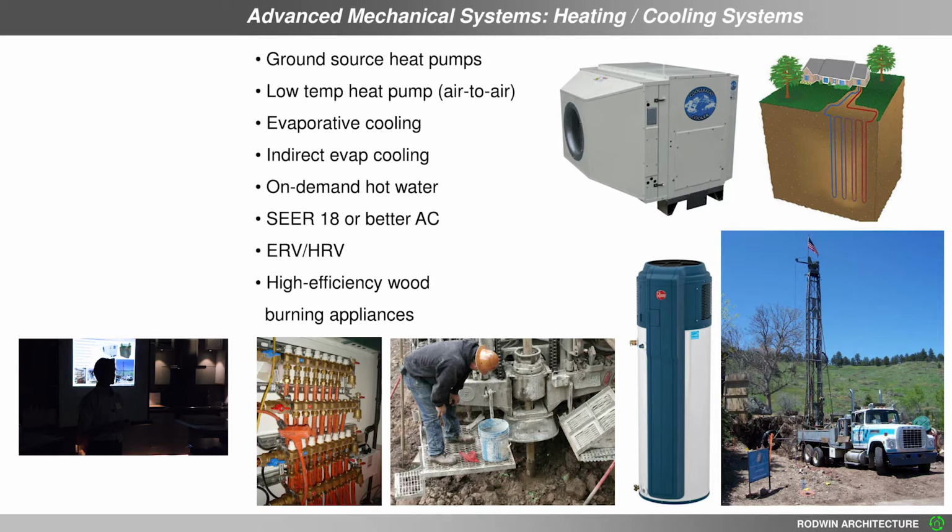It's inexpensive to install in new construction. It's harder with retrofits. With new construction, you can install this little pump that recirculates the water through your hot water lines. If you have a mechanical room on one end of the house and a bedroom and bathroom on the other end, you don't have to turn on the water and wait for 2 minutes for the water to get over there. It's already over there because it's constantly moving at a very slow velocity through the pipes in your house. So you turn on the water and 3 seconds later, hot water.